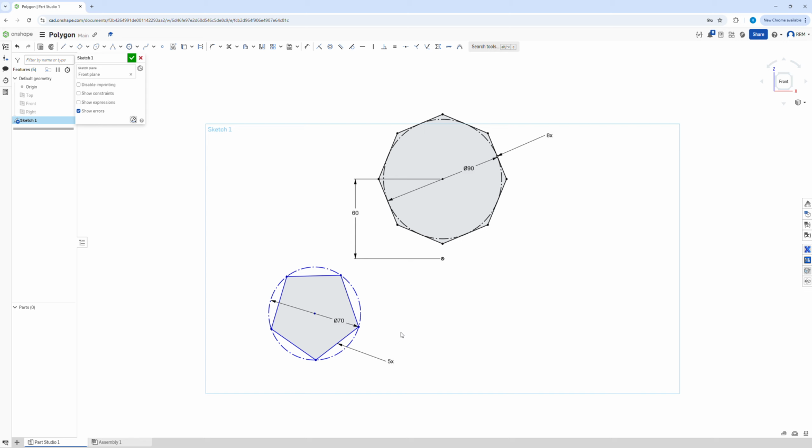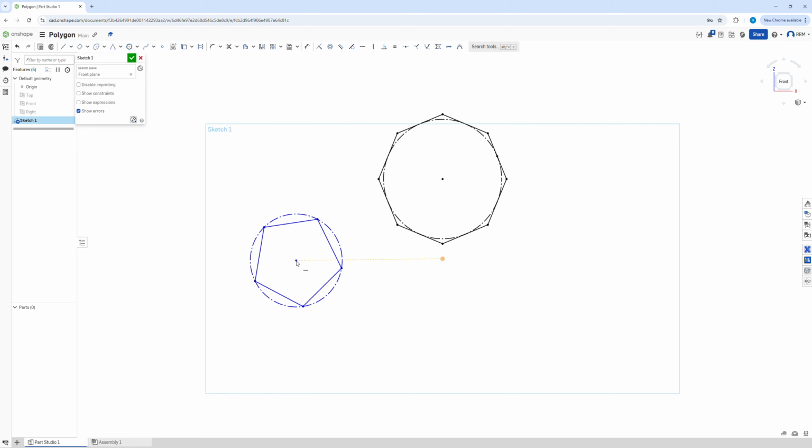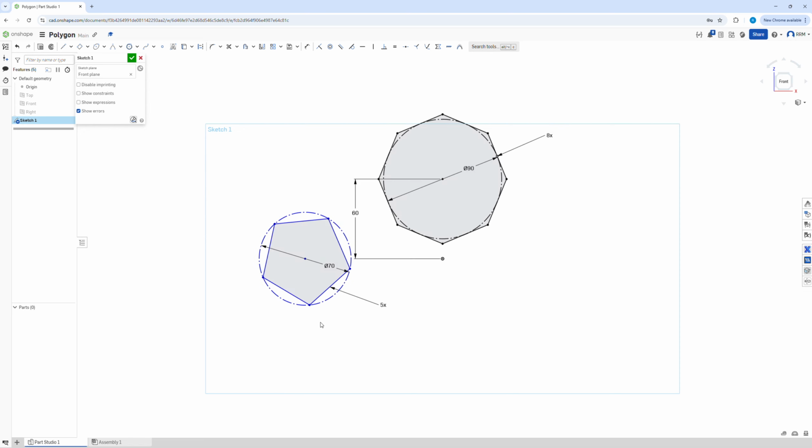It's all blue at the moment, so this time let's move this and make it horizontal. So I can auto drag it to my origin, let go. That's made that horizontal, so I can drag this across side to side. And now we need to make sure that it is at the right position. So we could do a couple of different things. Let's say that we want this line here to be vertical. So I click on that, press V, turns that vertical.